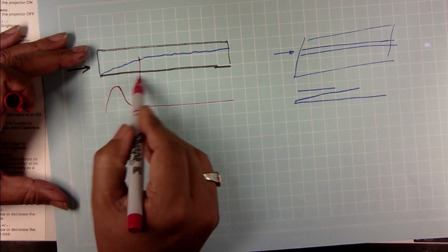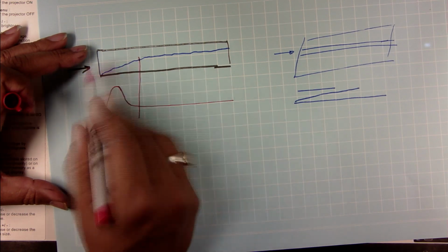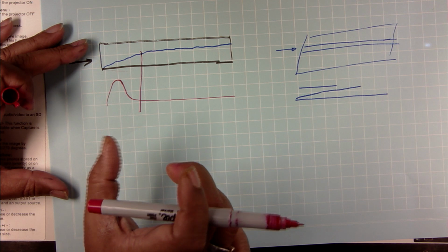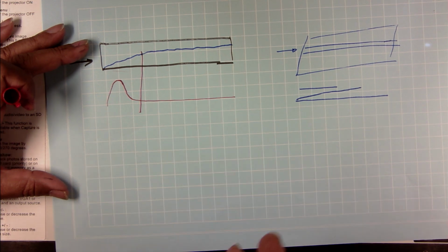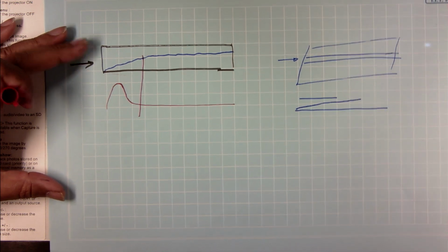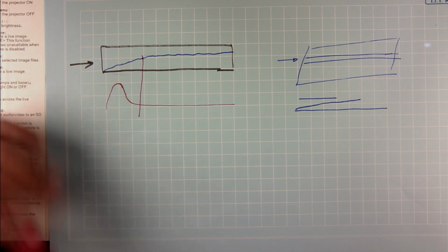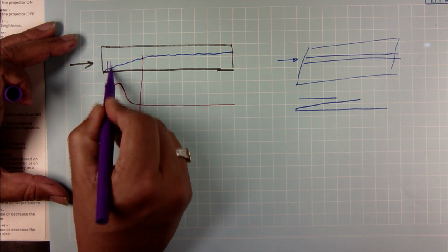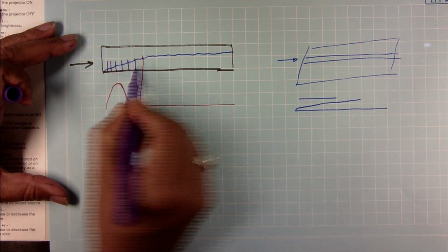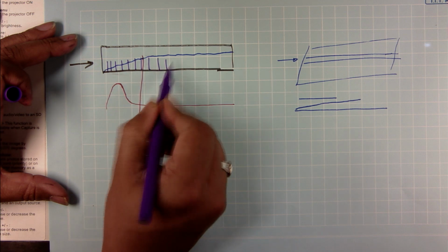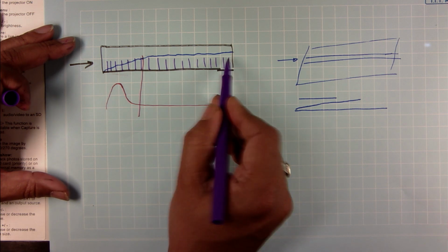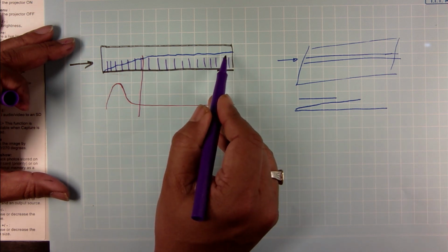So more than 50% of the heat transfer is probably in the first 10% of your heat exchanger. You see the problem, right? The bulk of the condensation or heat transfer is occurring very close to the entrance region of the heat exchanger. So now if I put a carbon nanotube coating in there, initially my carbon nanotube is sticking out like this as a fin, but at some point the carbon nanotube loses its effectiveness because it is buried under the liquid film.